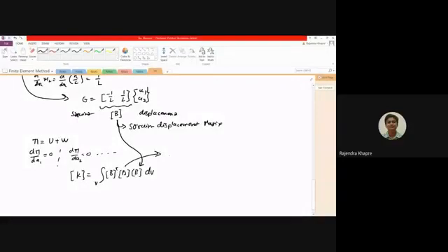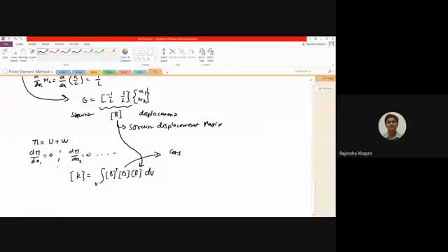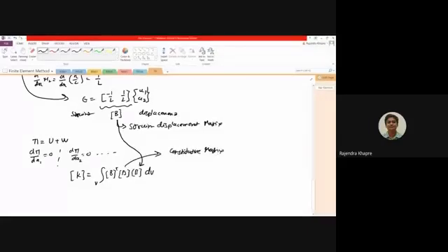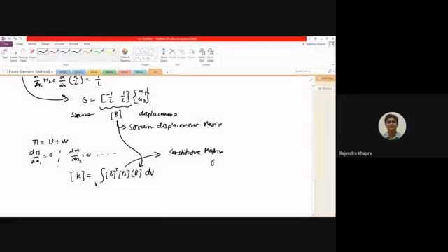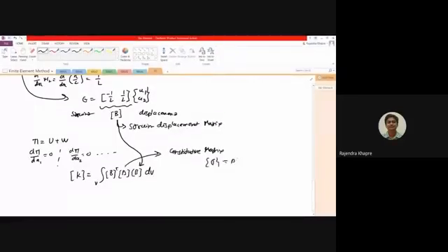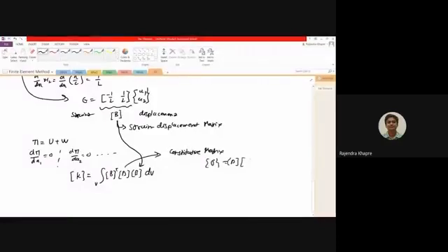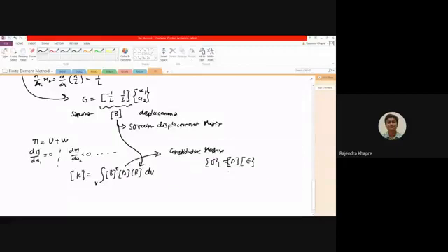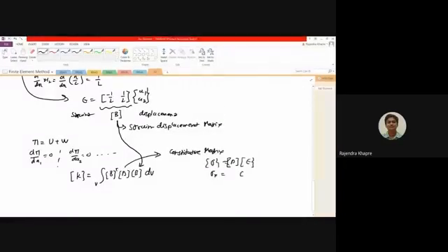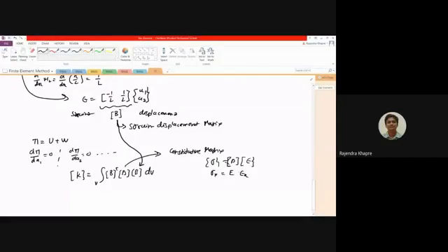Okay, so this is called the constitutive matrix. Generally it shows a relationship between stress equals D into strain. So this is simply a stress-strain matrix. It is also called a constitutive matrix. Now in case of a 1D problem, you have only sigma x and only strain in the x direction. So this value is nothing but a simple E.